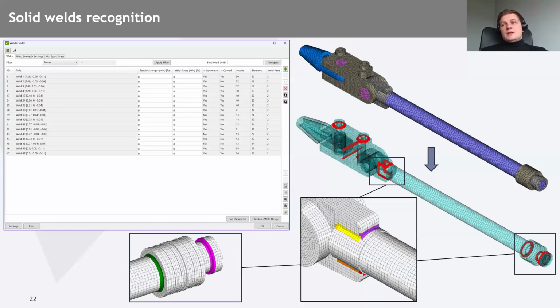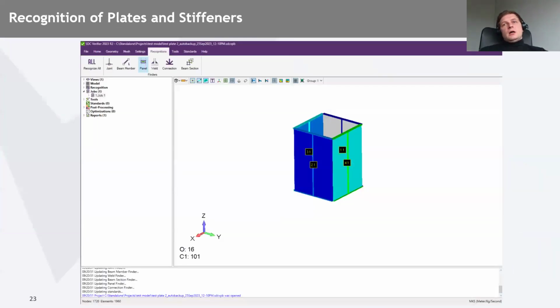But besides welding, there are so many structural elements to be defined. One of the options is, for example, plates for plate buckling. So not to identify only the buckling factor and the first plate that is going to buckle, but to identify the buckling factor for each and every plate of the structure. This is great especially for the naval architecture and shipbuilding industry, where you have hundreds of frames and millions of panels. You will have a utilization factor for all of them and only indicate those that are going to fail, and the buckling factor for those.